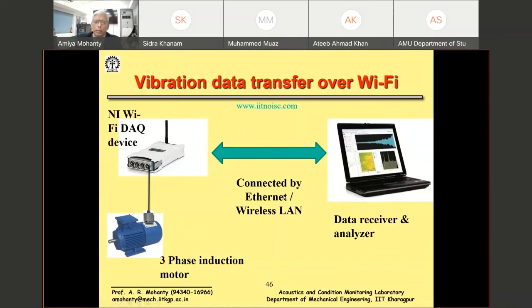And they could be over wireless LAN. This is in Alaska, and I'm sitting in Kharagpur. And to tell you, this is what we are doing right now. I am a consultant to many industries in India and in the US, where our algorithms are being used for motor current signature analysis to find out faults in motors and mechanical units being driven by motors. We have a server here. We tell them this is the problem with your pump at such and such location, or the motor at such and such location. That is the technology.